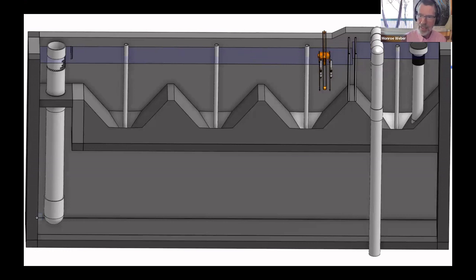Inside are all these pieces, and water enters through this pipe. And I should have made an animation here, but I got distracted. So water flows down into the entrance tank. I'm assuming you can follow my cursor. It's going to get deflected by this sloped bottom and end up heading over in this direction. And it's basically going to make a big eddy here and circle back and then go through. Here's some trash racks. Here's where the dose controller is for the chemical feed. It's picking off the water level there to figure out what it's doing.